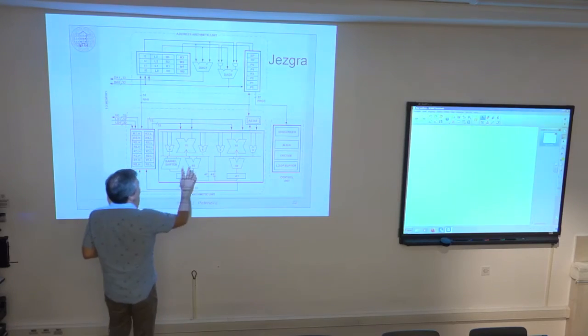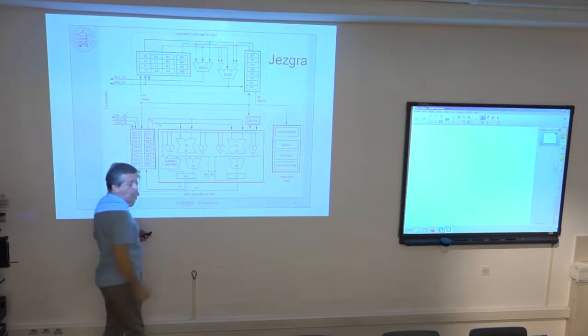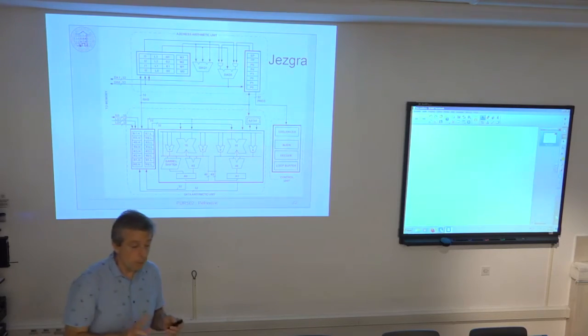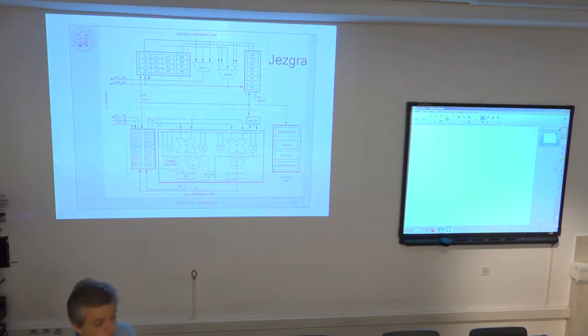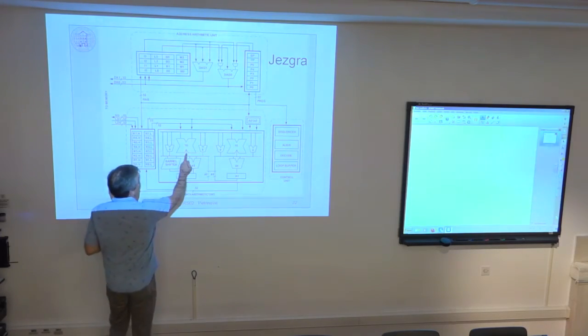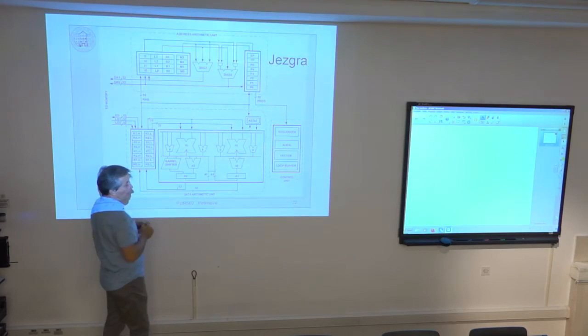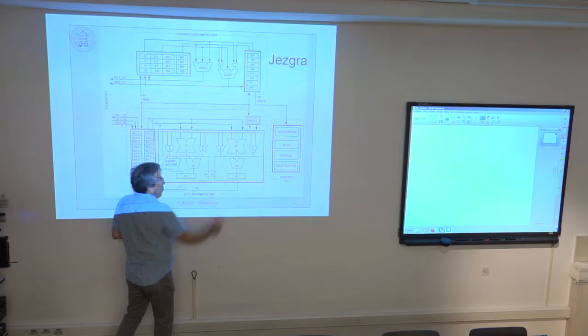They are of the same width as they were with this 21XX CPU. They support multiplication of two 16-bit input values, and they finally get one 32-bit double word product. And this product can be accumulated into the 40-bit accumulators A0 and A1.